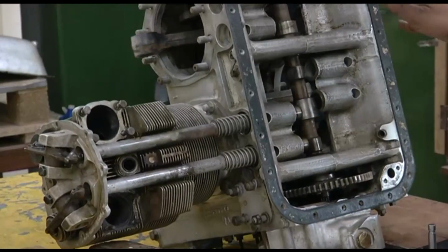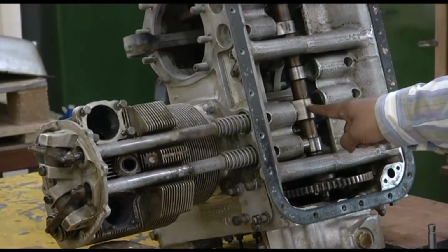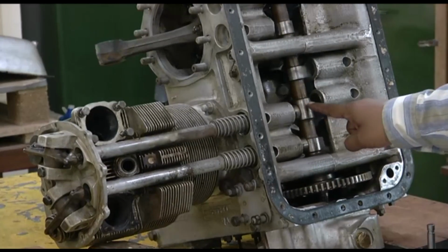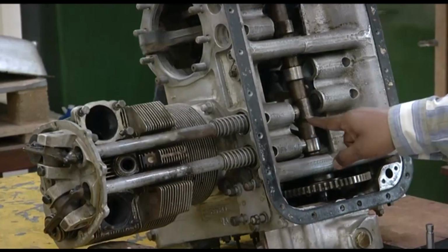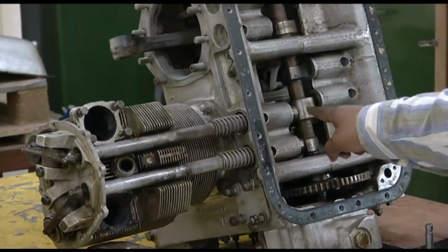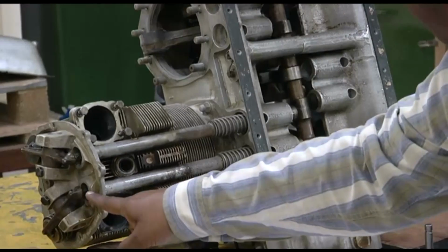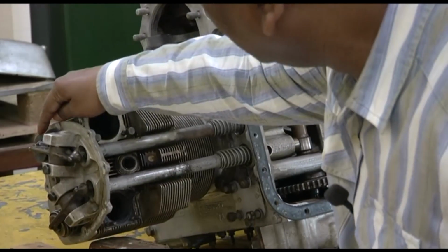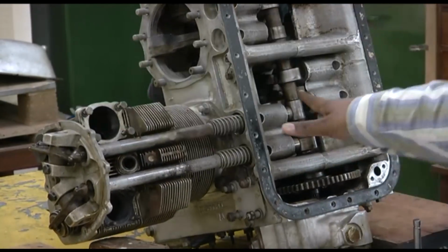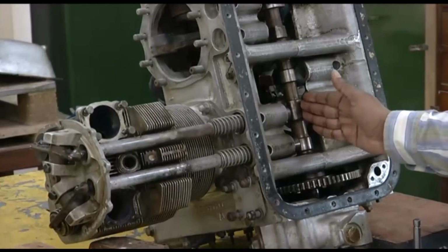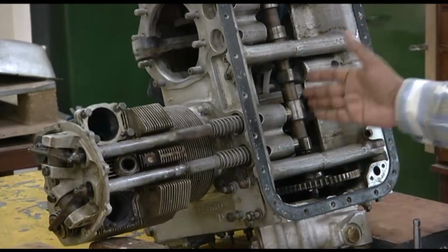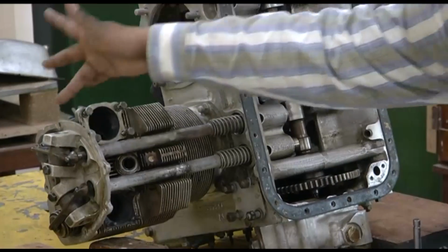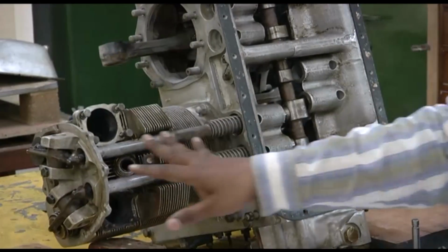So see, the engine is being turned. Now you can see the camshaft moving here. You can see the various cam lobes moving. Now the top end of the cam lobe pushes the valve lifter. You can see the valve lifter here, it is moving. Once the valve lifter is moving, you can see the push rod being moved. Once the push rod moves, you can see the rocker arm moving, and the rocker arm, when it goes down, you can see the spring also going down. So this is your complete valve operating mechanism: the camshaft, cam lobes, the valve lifters, the push rods, the rocker arm, the valve, along with the springs. So this is your valve operating mechanism.